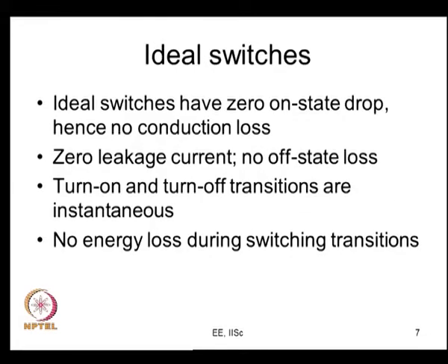As we said, the ideal switches will not have any forward drop, and therefore no conduction loss. There is zero leakage current, therefore no off state loss, and they turn on or turn off instantaneously. There is no energy loss during switching transitions. That is about the ideal switches.